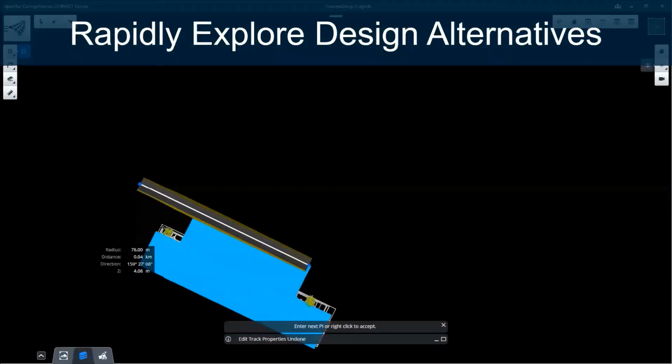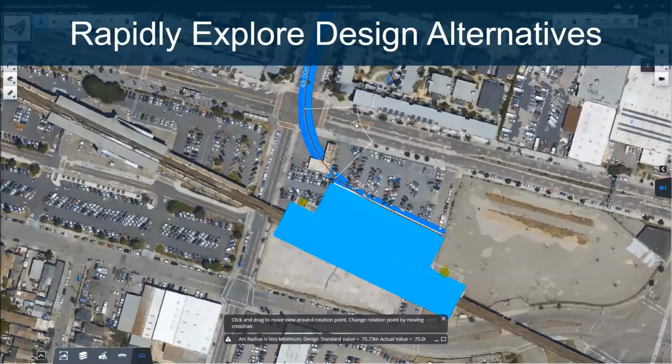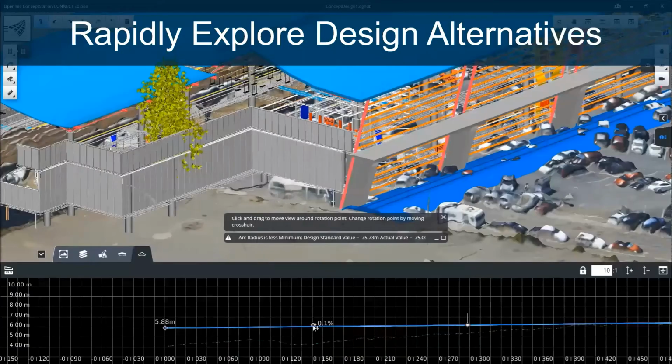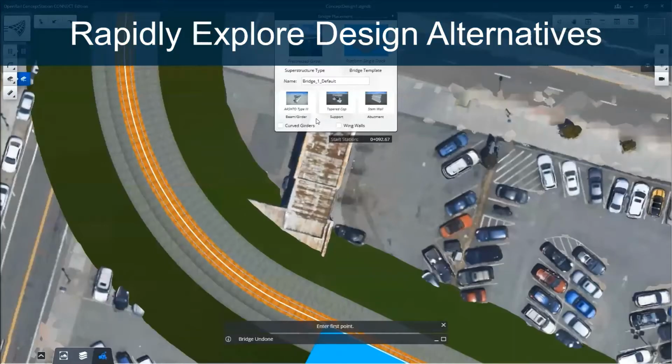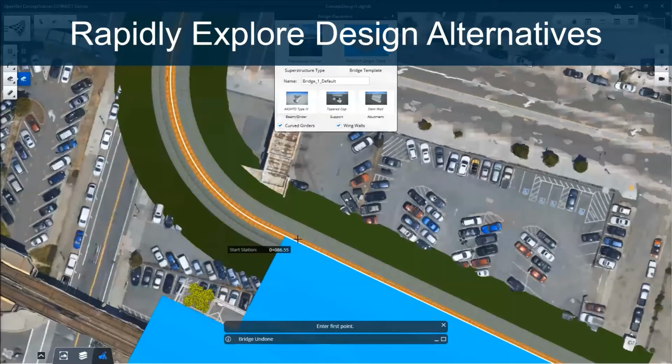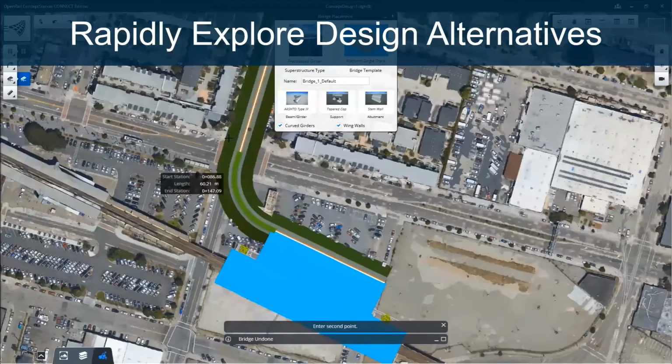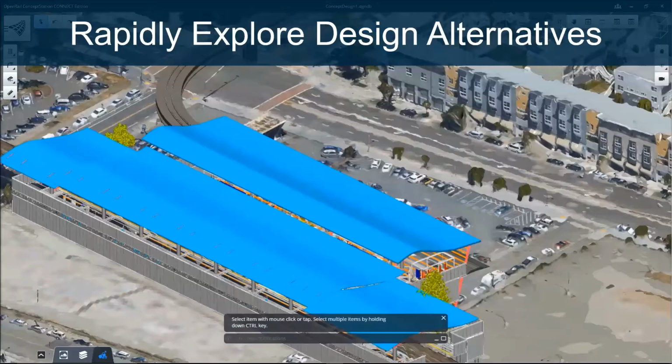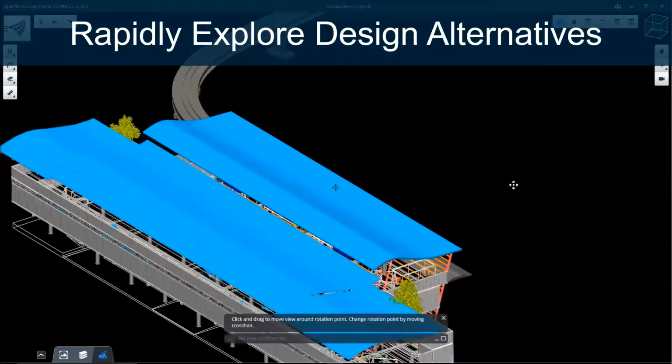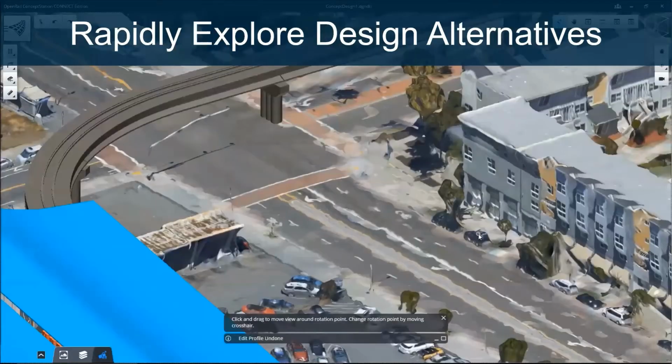You just click on the surface where you want to put things. This shows an overlay of a station in the design. Then you can do adjustments very quickly, as well as put in some simple infrastructure like retaining walls. You can also switch between different options like embankment and bridges.